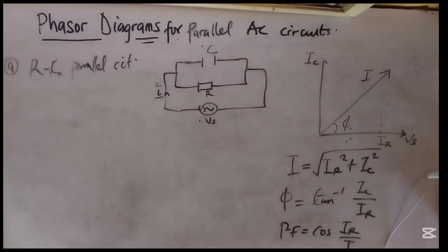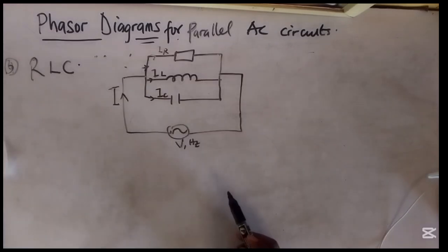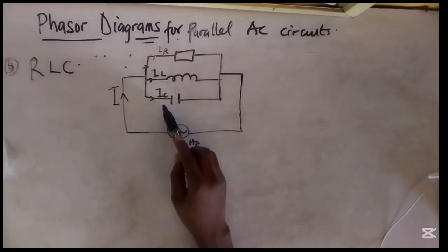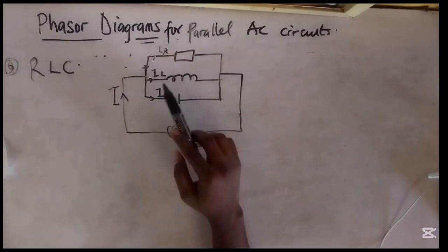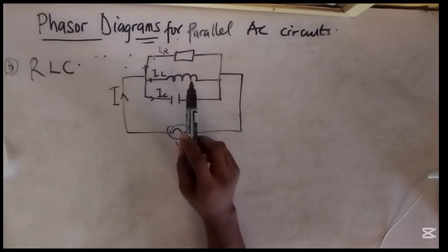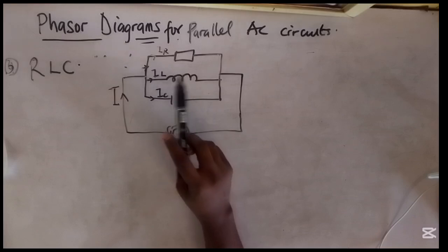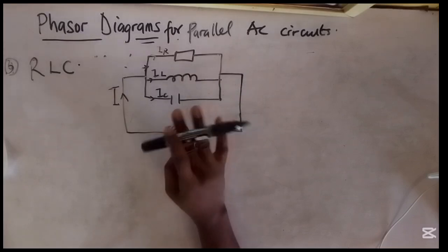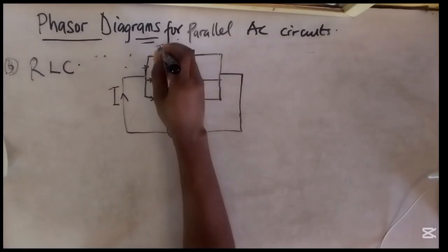I will show you the combination of R, C and L, and then we go into the examples where we have the connections in parallel. If you have an RLC circuit connected in parallel, how do we go about the phasor diagram? We can see in different cases, where our XC, for example, is greater than XL, the graph will look different from when our XL is greater than XC. The graph will look a particular way, and when it is vice versa, it will look a different way.